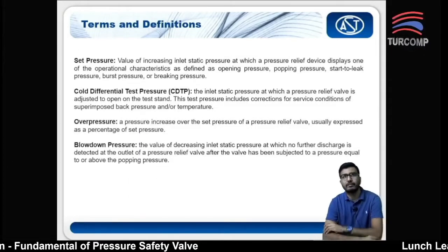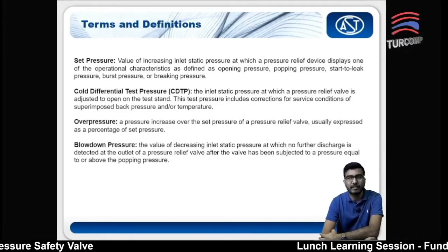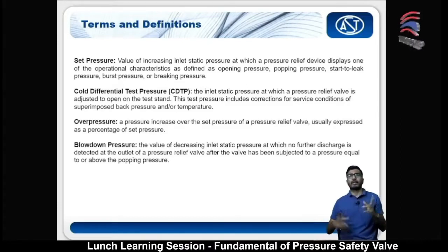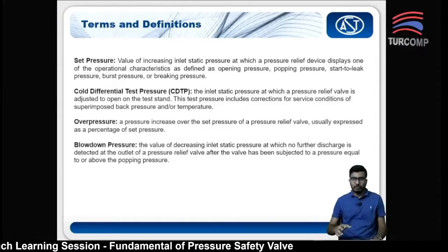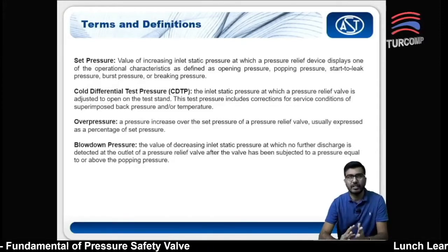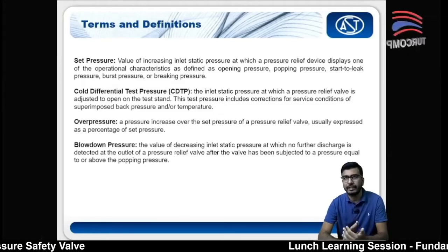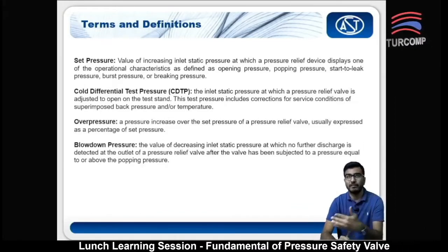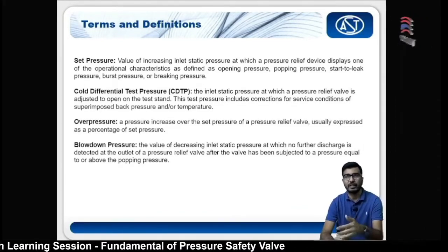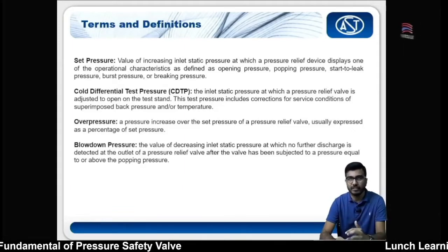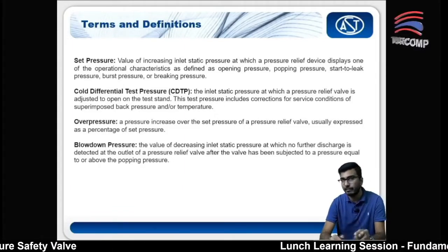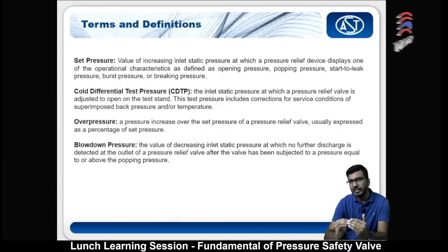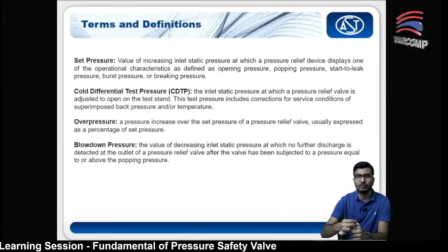So one of the other terms that we have is basically these terms. When you talk about the relief valve, you will have these 4 pressure terms. So let's just look at the first one, set pressure. Set pressure is the value of increasing inlet static pressure, meaning increasing pressure at your inlet, at which the pressure relief device relieves. One of the operational characteristics is defined as opening pressure, popping pressure, start to leak pressure, burst pressure or breaking pressure. Meaning set pressure is the point where it's just started to open, meaning it started to lift